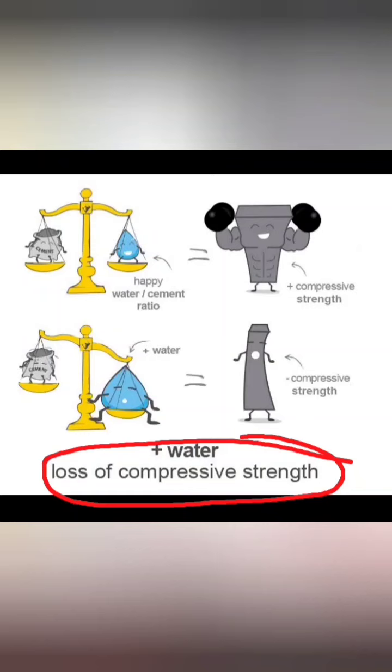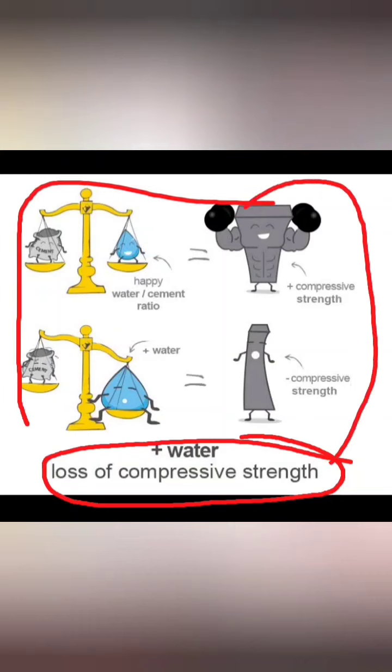But for high performance concrete or high strength concrete, we will go for a water cement ratio as low as 0.4. In this condition, workability will be less. For that, we are going to add admixtures. So with this, finally we can say the water content should be less to have more stiffness and more strength of the concrete.